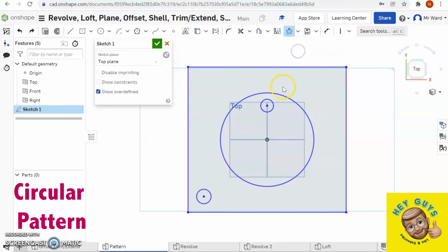So I'm going to grab the circular pattern from there, and it defaults to 3, and it defaults to going all the way around. Now if I grab this arrow, and I'm not going to because I don't want to do that, that will change how far around the circle I want it to go. So that's by degrees. So if I only wanted, let's say instead of 10 all the way around, 5 that just go 180 degrees, I'm going to bring that down to where that's 180 degrees.